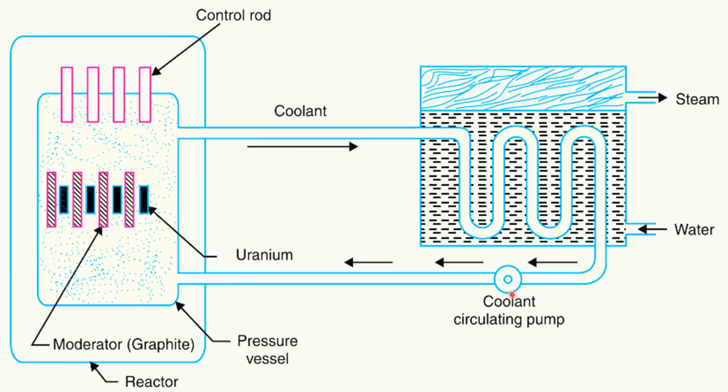The coolant is made to flow by a coolant circulating pump, and this coolant is flowing into this pressure vessel, and then it removes all of the heat energy inside this pressure vessel, and then it flows out of that vessel via these pipes, around which we have water, which is injected from this port, and then steam is generated, collected at the top of the cylinder, and then the steam is emitted from this side. So this steam is then used for power production.